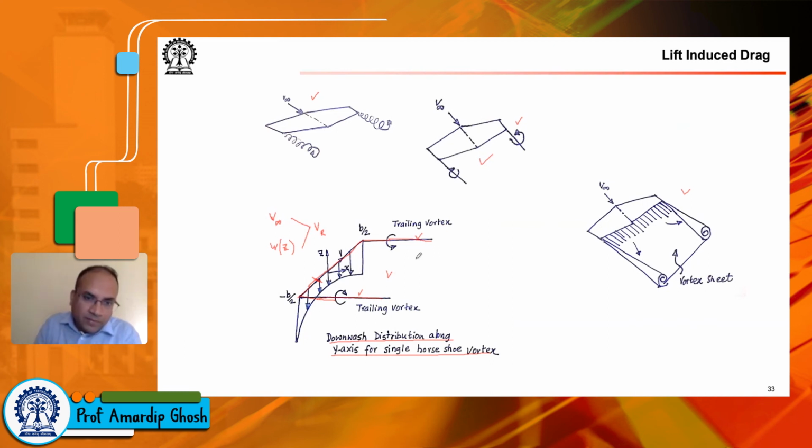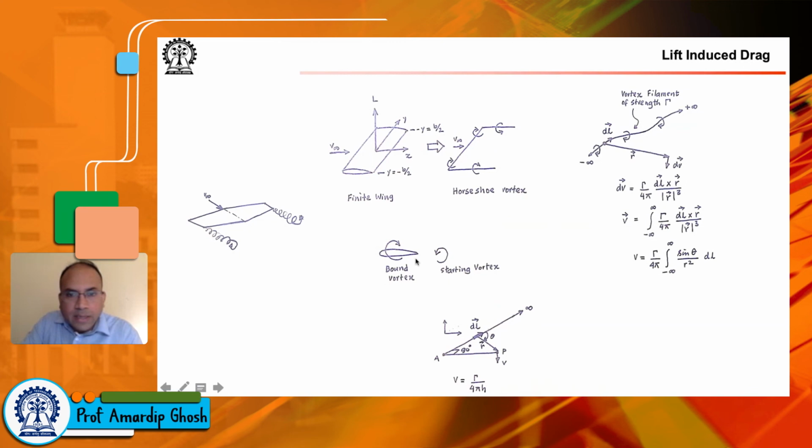So a component of lift will come into play as the drag. It is unfortunate that although we want lift, the moment you have lift, you have this lift induced drag, and it depends on the amount of downwash, and the amount of downwash also depends on the amount of lift. So this is a very strange situation, but nonetheless, it's what we will see in the corresponding lecture.